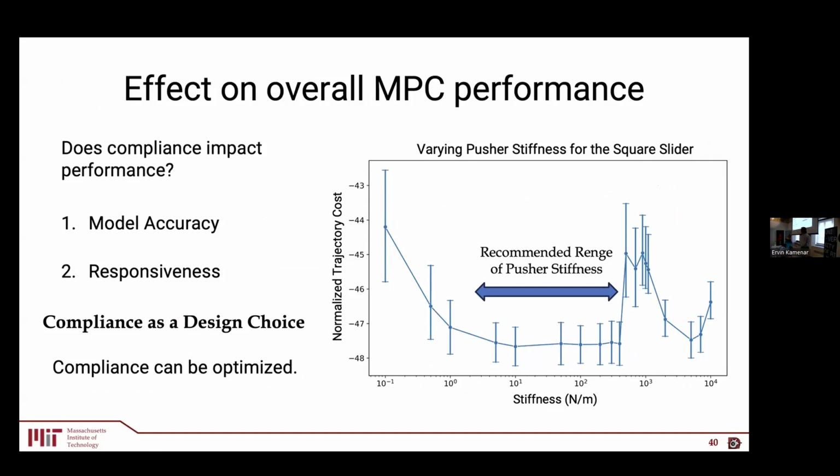So we learned two things. Yes, if stiffness is too high, this method does not apply. But at the same time, in the context of robotics, compliance at the tip may be a design parameter. You can pick the right one to guarantee good performance.